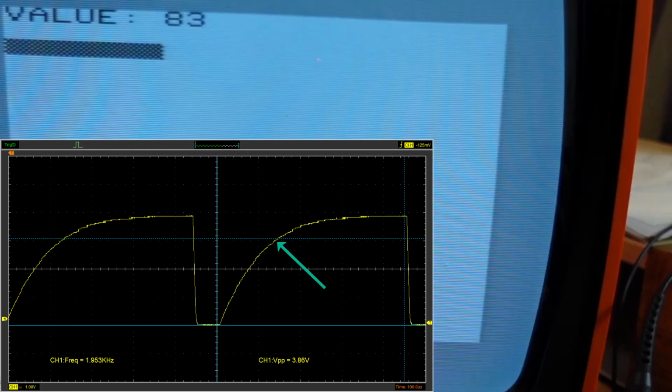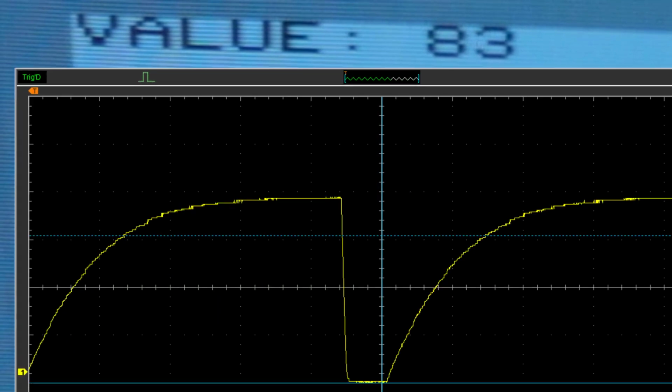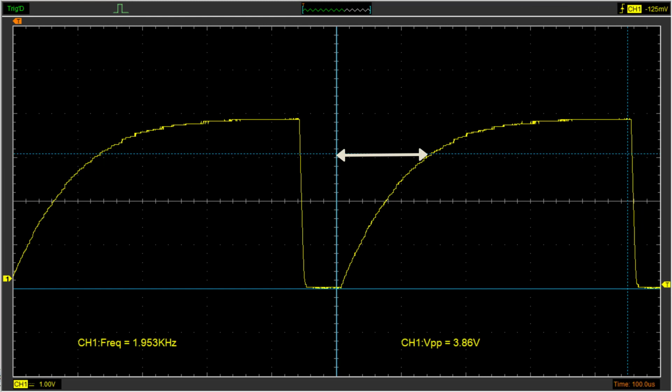At this moment, an 8-bit counter value is copied into a register and can now be read by an application. This value represents the time that's needed to charge the capacitor and is proportional to the actual resistance. When the counter reaches its maximum, the capacitor is discharged, the counter reset to 0, and the whole process starts over again.